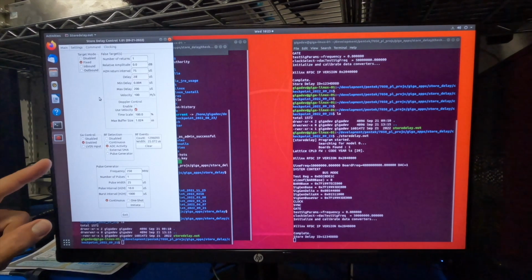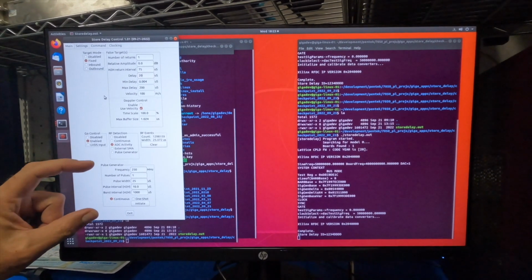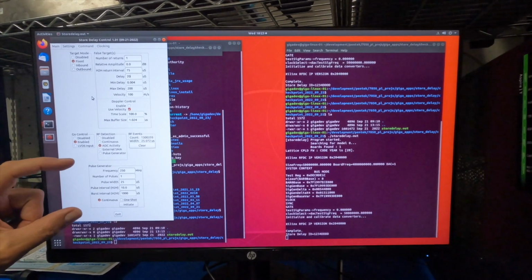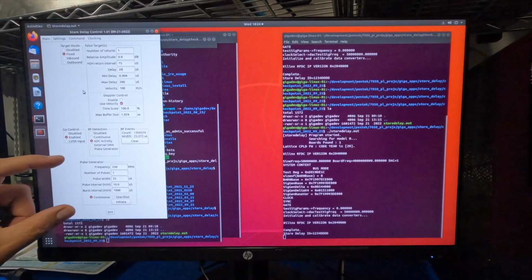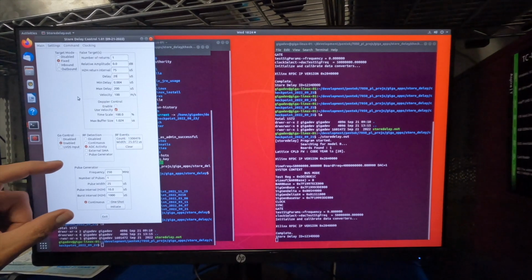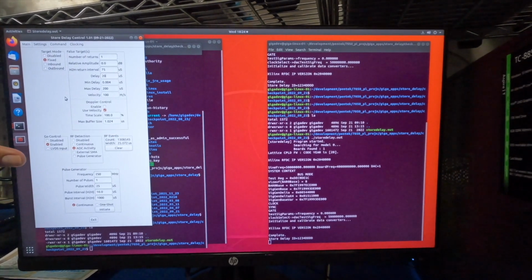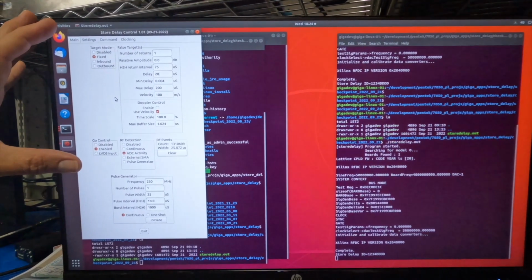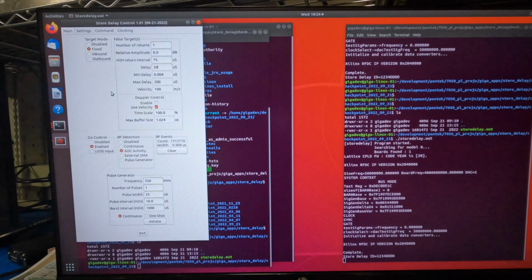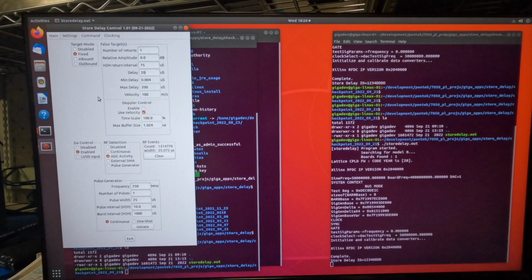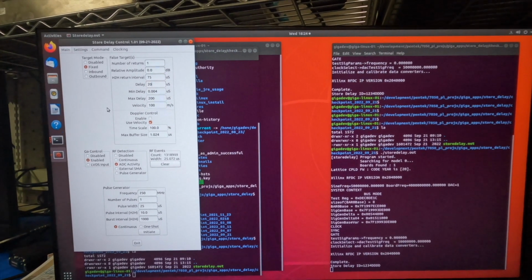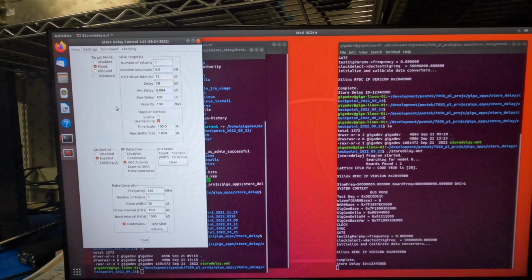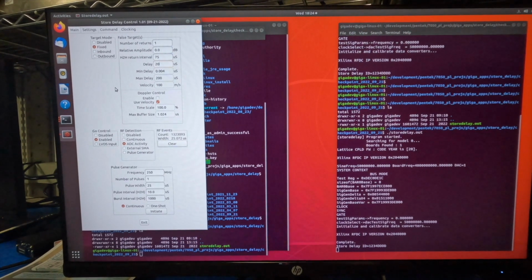So again, past the section of code that's generating the input signal that the electronic warfare system is going to be seeing and modulating after it stores it and plays it back, the other portion of the GUI, which is the most important portion of the DRFM jammer, is the target mode, which includes disabled, so it won't be playing back anything that it captures, a fixed target playing it back, and both inbound and outbound targets.